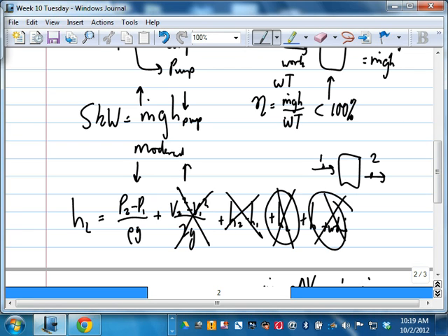for the 5 kilowatt rated pump, we can either have a very high m dot, move a lot of fluid, and the pressure difference is small across the pump, or we can move a little bit of fluid and have a big pressure rise across the pump. All right, same argument, whether you want to talk in terms of head or in terms of pressure, because for the pump, the head is just the pressure rise. Is that okay so far?